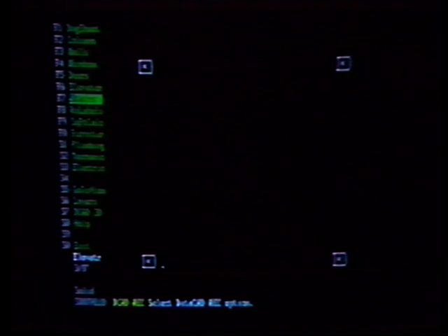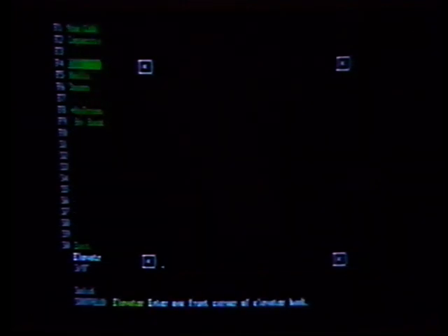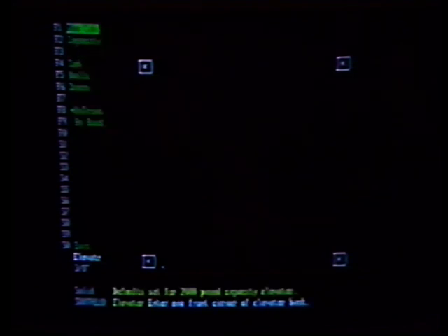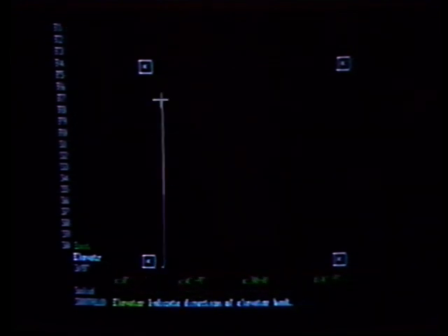To create the elevator, I'll just go to the elevator menu on DataCAD AEC, where I see up at the top selections for the number of cabs and the capacity of each elevator. Let's say we have 2 cabs in this building, and the capacity of each elevator is 2,000 pounds. That's all I have to do. DataCAD can dimension the elevator based on that information, so that all I need to do is locate where the front of the elevator is, which direction it faces, and DataCAD will produce the 2 elevators, the cabs, the doors automatically, and all those pieces and parts are customizable by the user.